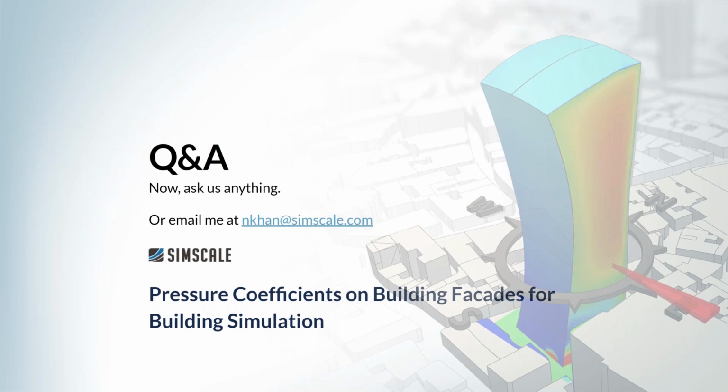So we can import a windrose, and what that means is we can take in the annual wind data for any location, so wind speed and wind direction, and we also have a database connected to SimScale. You might remember Darren showed one of the steps was define windrose.